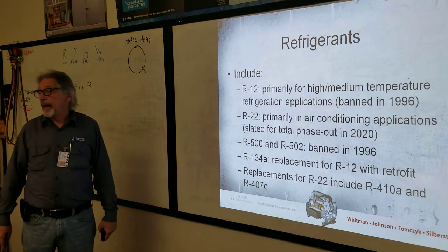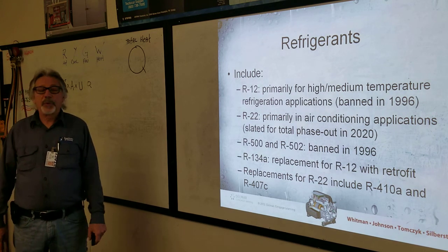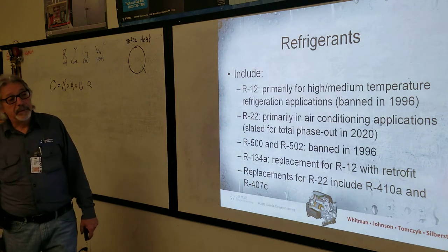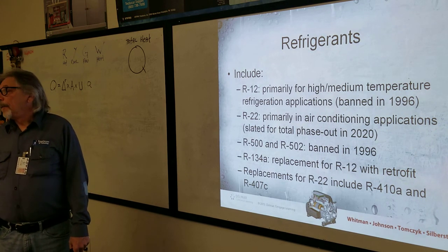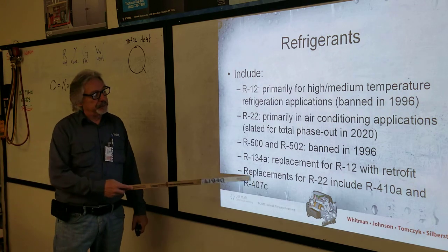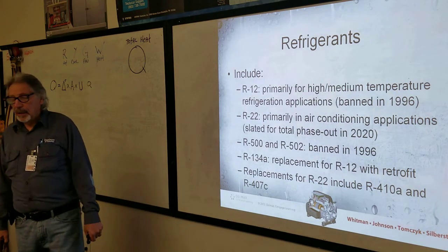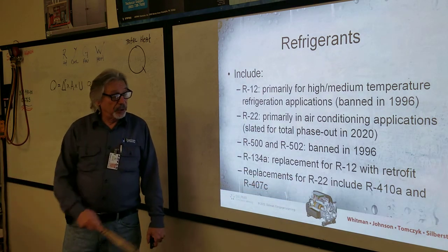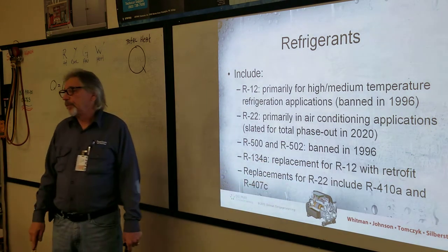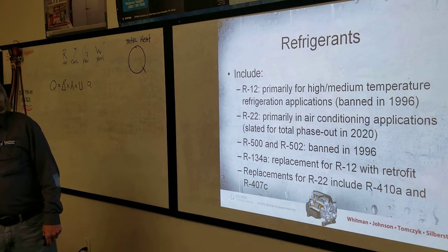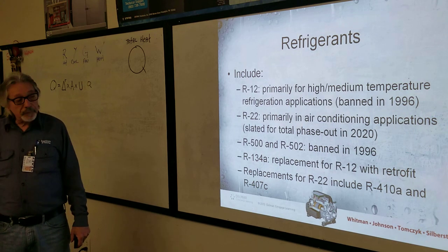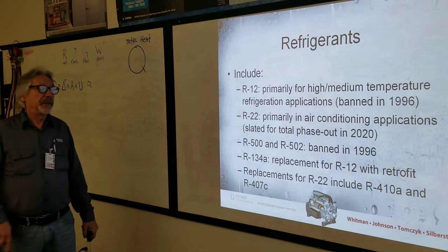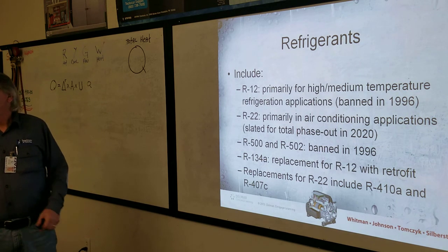But then we don't have to dump the oil on that then, right? No, not on 427 or 428 or 438 or 450. Yes, the 407C requires alkylbenzene oil. And what's in the R22 systems, the older R22, 12, 50, 100, 502 are all mineral oil. So the refrigerants aren't really compatible with that type of oil. You want one that's gonna be compatible.